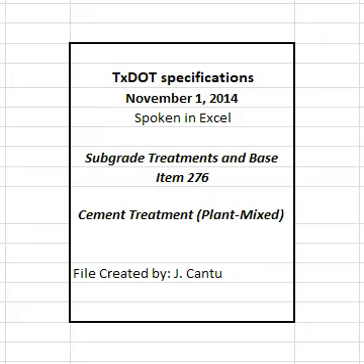2. Materials. Furnish uncontaminated materials of uniform quality that meet the requirements of the plans and specifications. Notify the engineer of proposed sources of materials and of changes in material sources. The engineer will verify that the specification requirements are met before the sources can be used. The engineer may sample and test project materials at any time before compaction. Use TEX 100E for material definitions.